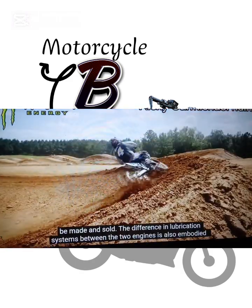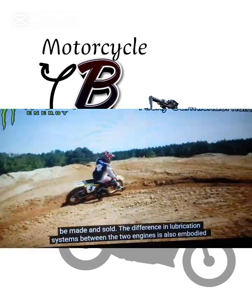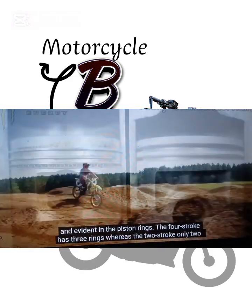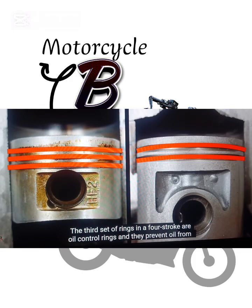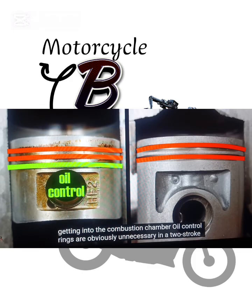The difference in lubrication systems between the two engines is also embodied and evident in the piston rings. The four-stroke has 3 rings, whereas the two-stroke only 2. The third set of rings in a four-stroke are oil control rings, and they prevent oil from getting into the combustion chamber. Oil control rings are obviously unnecessary in a two-stroke because the oil gets into the combustion chamber anyway, with or without them.